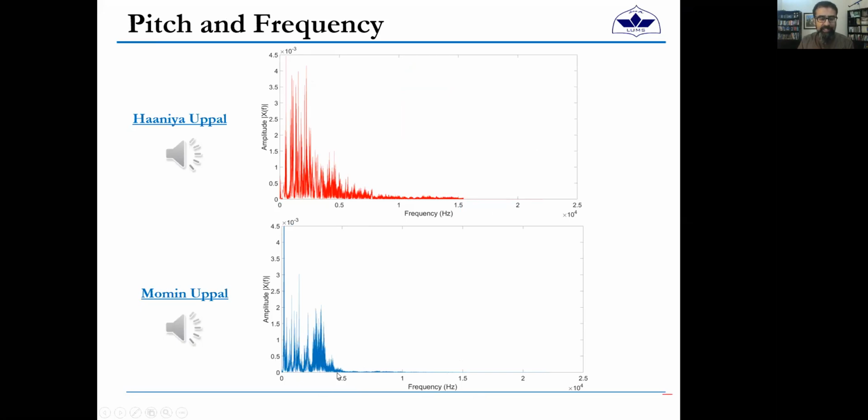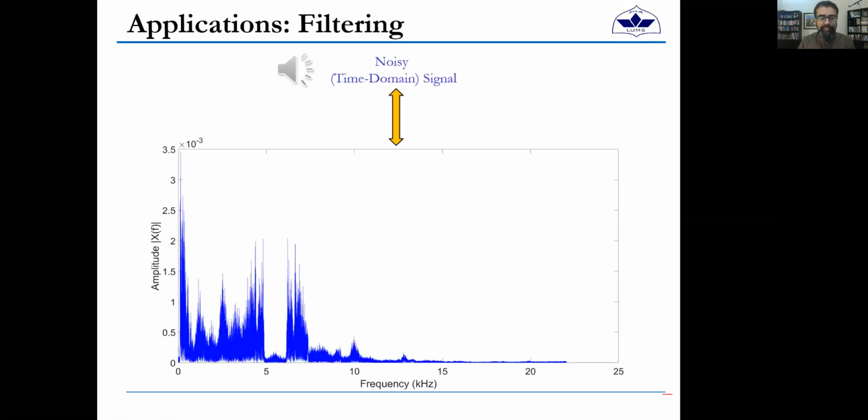From my previous figure, over here, I know this was my uncorrupted voice, and you can see that this was centered around 0.5 kilohertz, almost, or actually I would rather say it's below 4 kilohertz. This would maybe just be noise, right? So I know from the previous analysis that the maximum frequency for my own voice is around 4 kilohertz. From that, I can conclude that everything that appears after this 4 kilohertz, from here to here, is perhaps that dog whining. And let me try to separate it out, therefore.